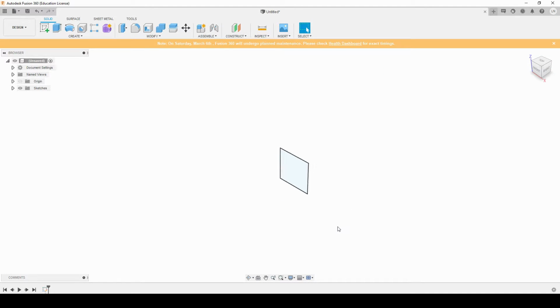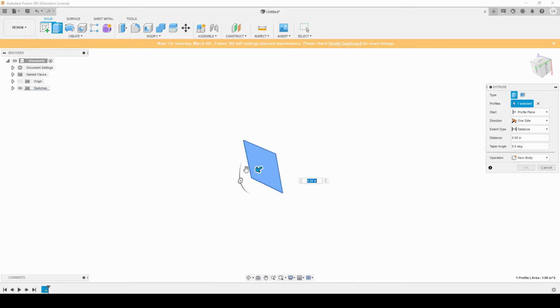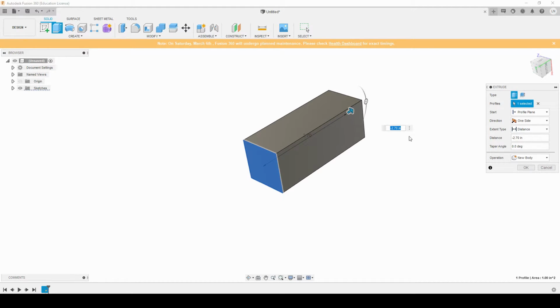Now, what you have here is a 2D sketch in a 3D space. To move stuff around, I'm clicking middle click to drag, and shift and middle click to rotate. As I mentioned before, all CAD is just getting 2D shapes and extruding them outwards into 3D shapes. So to make your 2D shape a 3D shape, all you gotta do is come up here. You've got a multitude of tools to use, like the revolve tool and the extrude tool. All we're going to focus on is extrusions, because extrusions let you click on the face that you made before and then stretch it out into 3D space.